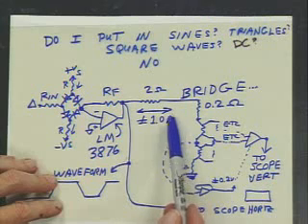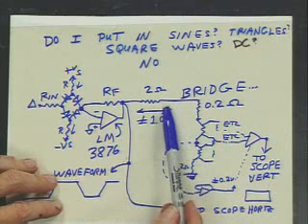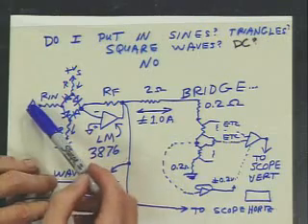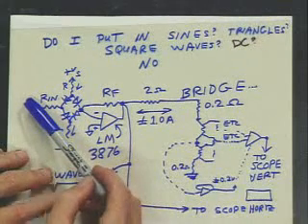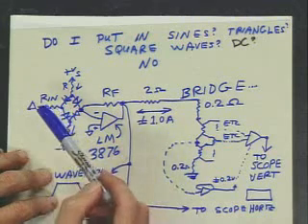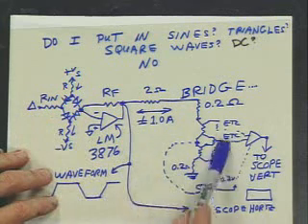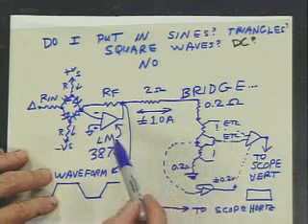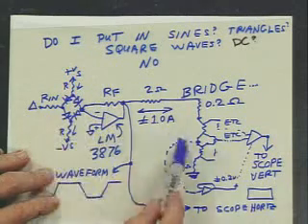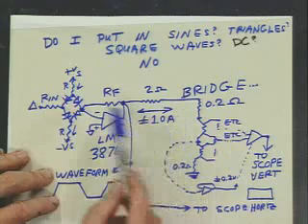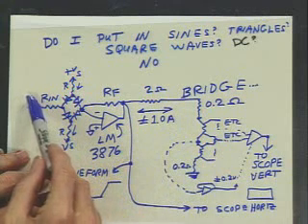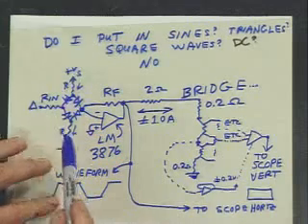Now, why? Well, I'm going to run it at 3 hertz because I've found best low signal to noise at 3 hertz. If I run this at 300 hertz, it'd be lousy because I run into the inductance, all the stray inductance. But at 3 hertz, I can still see the inductance of this, but it's not excessive, and I get good signal to noise from running this at 3 hertz. That's why I picked that frequency.